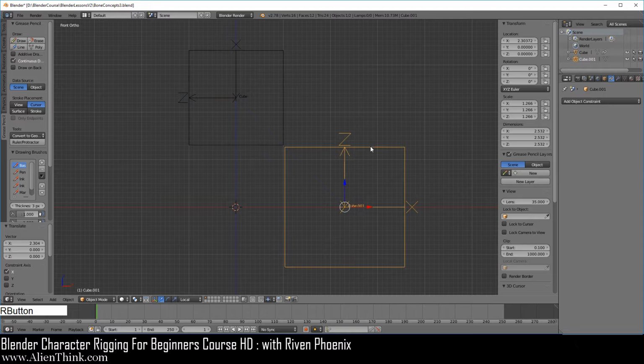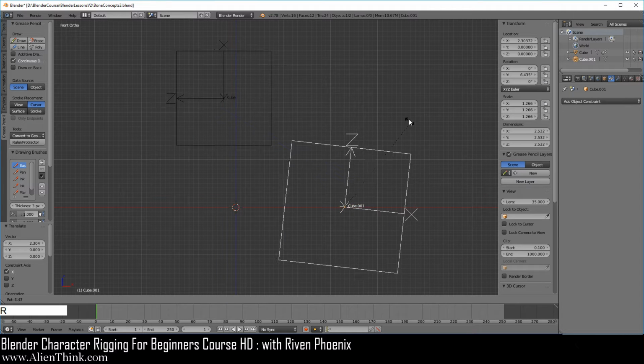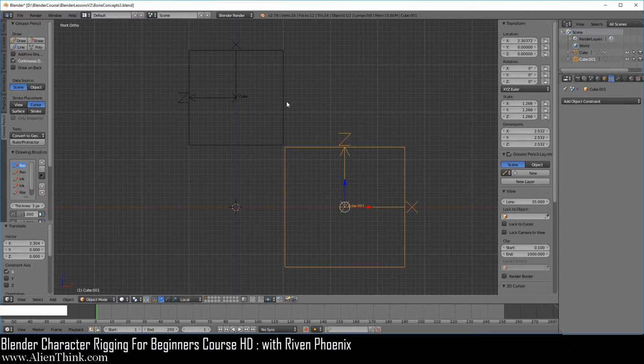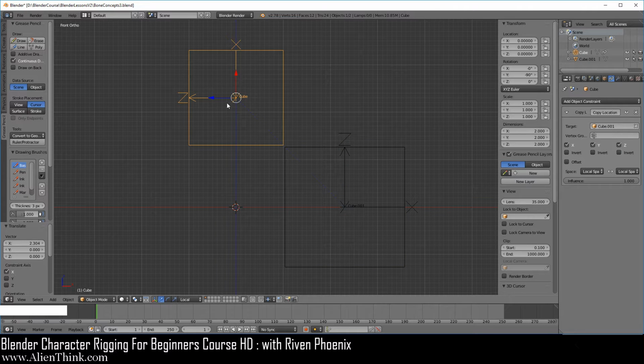Meaning that if we click on this object and press the R key, you'll notice that it's going to start to move this object, and you know exactly why it's doing it, right? So here we're going to expose first its local coordinate system, that we know Blender is simply going to take the Z and X axis and make that the local coordinate system. And it's obviously going to be at the center of the grid. Same exact thing is going to happen for this object.